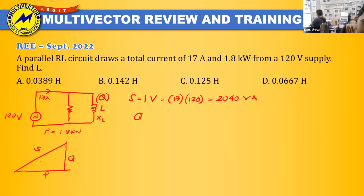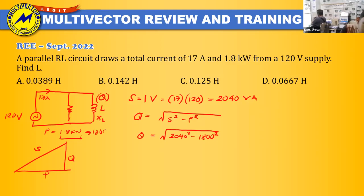Our Q, based dito sa ating right triangle, yung power triangle natin, is just equals to S square minus P square. Therefore, our Q is just the square root of S square, which is 2040 square, minus yung real power natin, which is 1.8 kilowatts or 1,800 watts square. Therefore, Q is just equals to 960 volt ampere reactive.